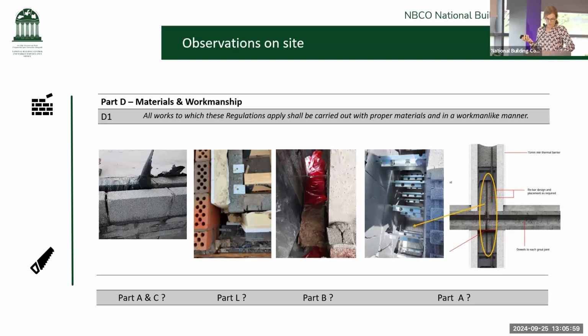So other issues that we're noticing: missing rebar in ICF has been noted on a couple of inspections that I've been on recently. Again, the information, the agrément certificates, not being followed. It's possibly difficult to see that, but again, in this instance, there was no rebar evident before the concrete was poured. So it just highlights the importance of the inspections.